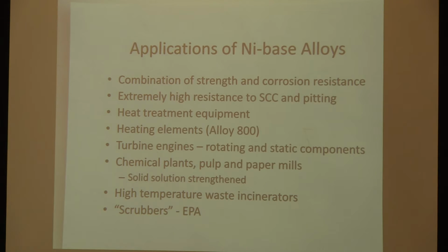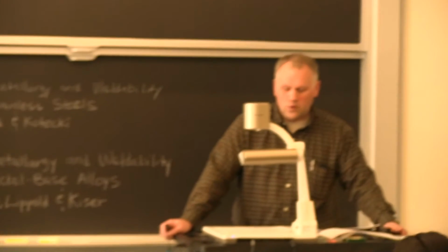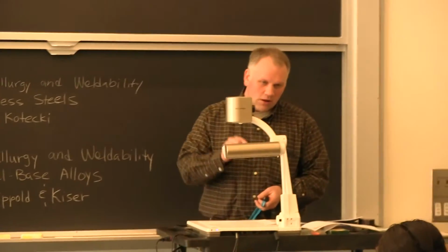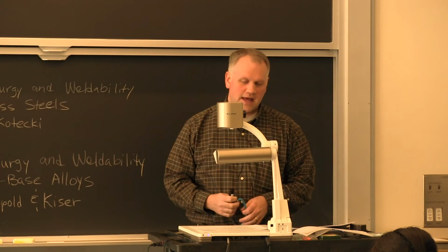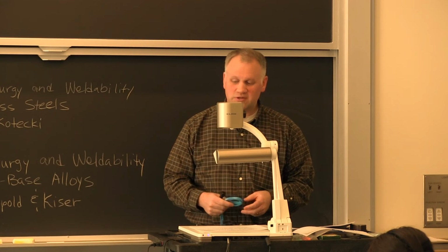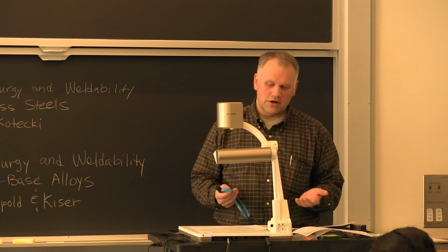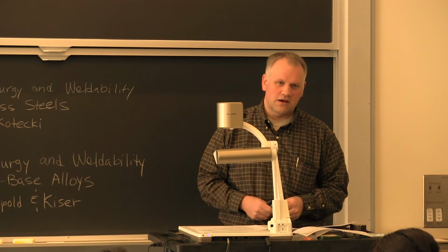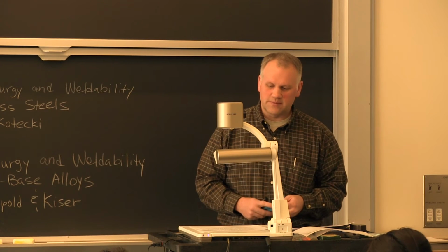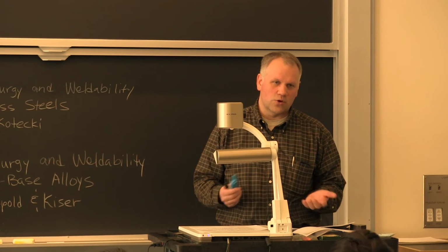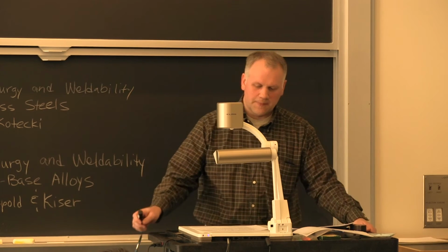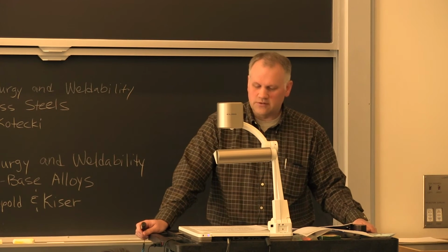What's pitting? Pitting is a corrosion process where small pits are created in an alloy. Certain stainless steel alloys are susceptible to that. Austenitic stainless steel alloys are susceptible to both stress corrosion cracking and pitting in chloride environments. But the nickel-based alloys are resistant to that.